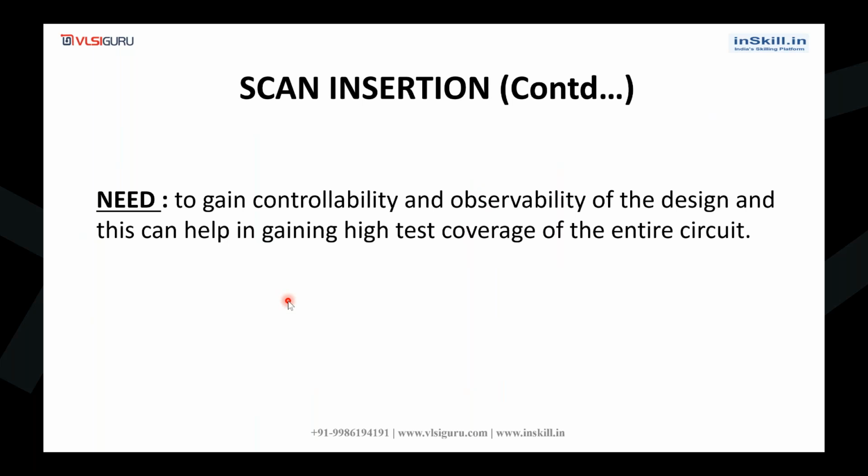We need to go for scan insertion in order to gain controllability and observability of the design, which means in order to easily control and observe our design. We'll try to understand this point with the help of an example.